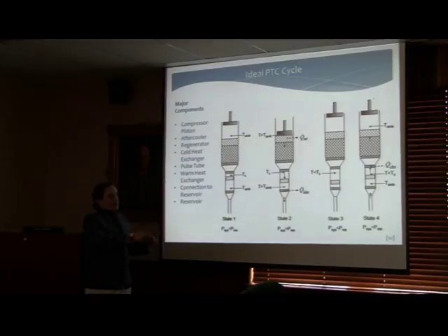And at this point, it becomes cold enough to accept the cooling load, so it's going to accept heat from whatever it's trying to cool, thus cooling it. And then the mass is going to start moving back upwards, and eventually the temperature is going to sort itself out back to ambient, so the pressure will again equal the pressure of the reservoir back at stage 1.